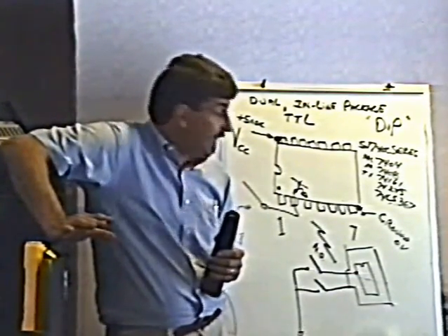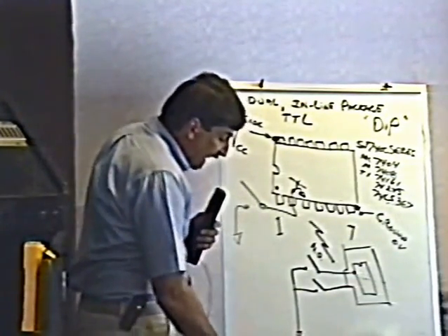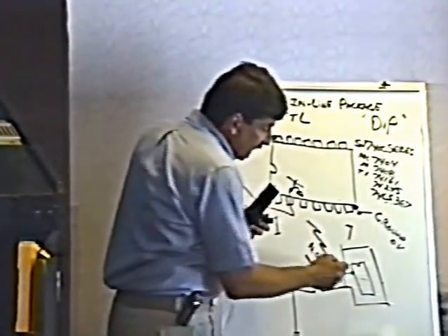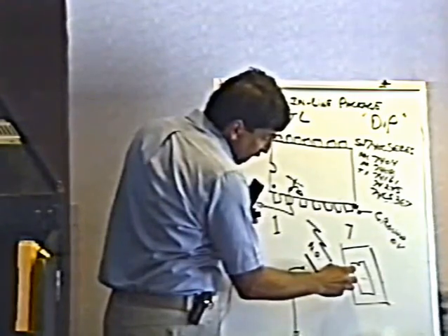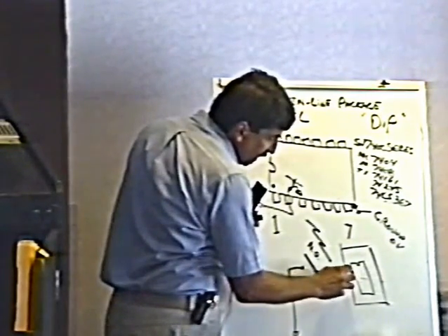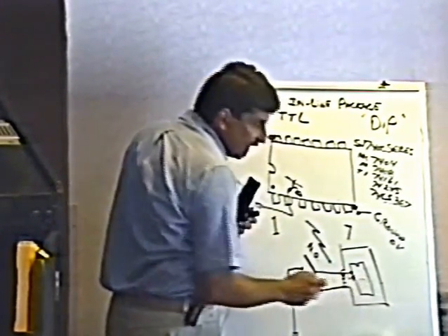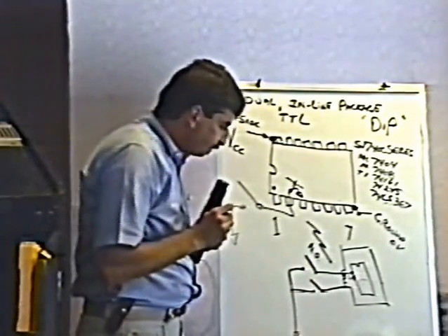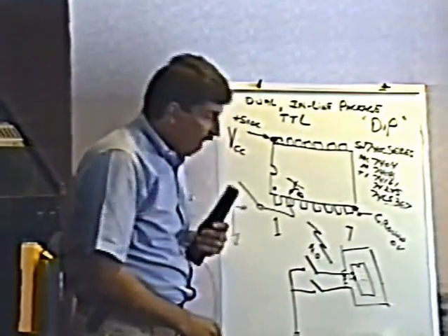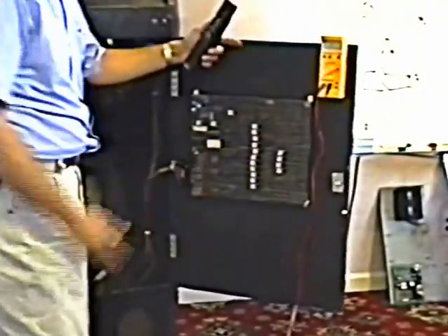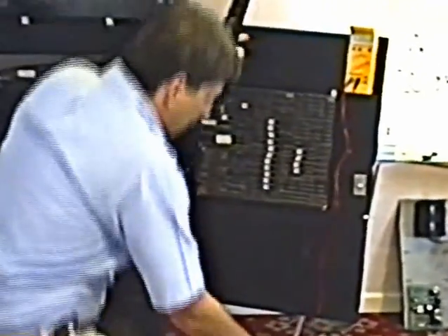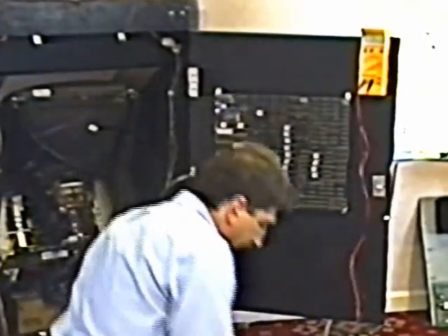Well, this is an unbelievably neat trick, and you can find that pin, by the way, if you don't have the schematic, which you probably don't, simply by following the trace back from the edge of the board, follow it back, and go right to the pin of the IC. Regardless of that, in fact, you can check them really fast. You don't even have to be very careful about it. Since the power is off now, there's no power on right now at all. You don't even have to have the game hooked up.